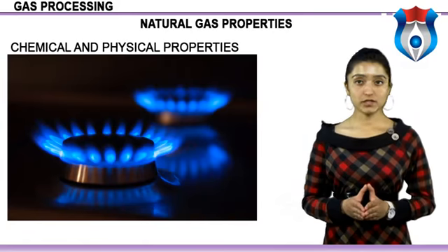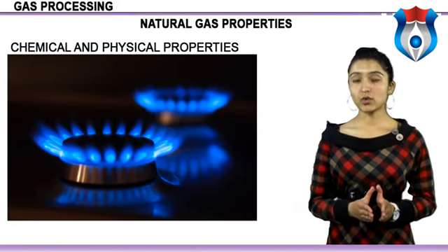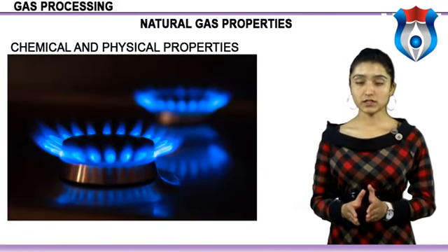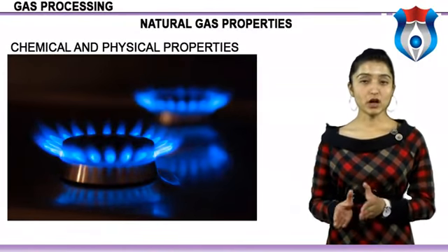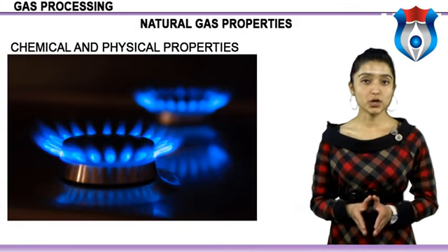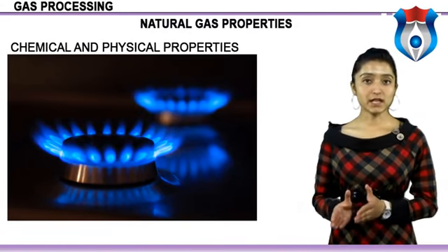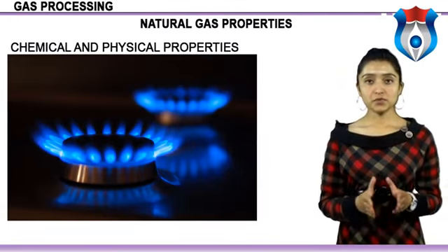This diagram shows the area within which variations in the Wobbe index and the flame speed factor of gases may occur for the given range of appliances without resulting in incomplete combustion, flame lift, or the lighting back of pre-aerated flames.